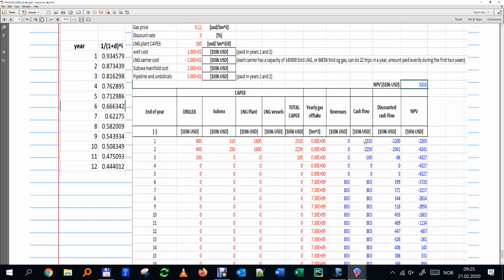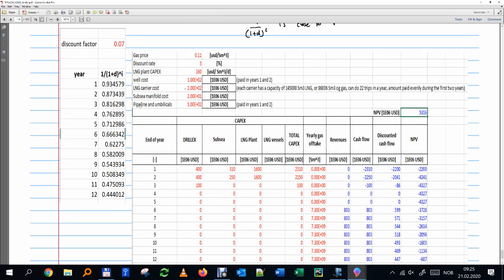Expenses include the cost of drilling wells and the cost of the subsea system, which had the pipeline, this long pipeline of 158 kilometers, and the umbilicals. We're going to see later what the umbilicals are, but basically all wells have valves, meters for pressure, temperature and rate measurement, actuators for the valves, and chemicals that you inject in the wellbore.